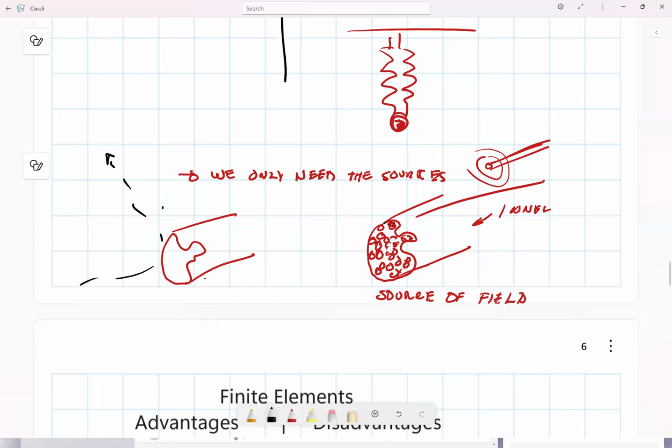A question: for integral equations, usually you don't get a single value that represents all your integration volume or area? No, yes, you would get. You just add them all. So is it a good method for getting energy and circuit parameters, in general, as long as it's linear? Like if I want to get, let's say, leakage inductance or self-inductance. The advantage is whether or not you can discretize the source easily or not.